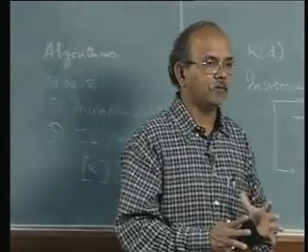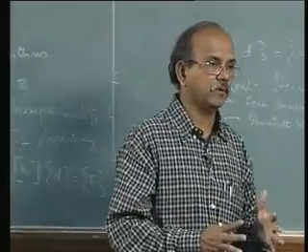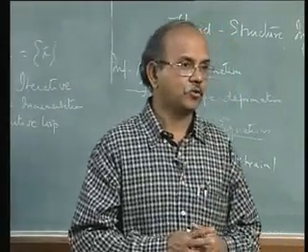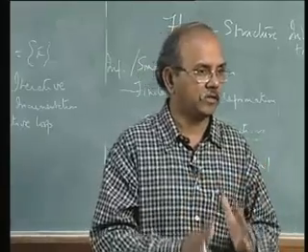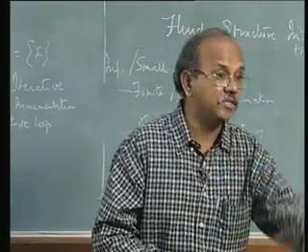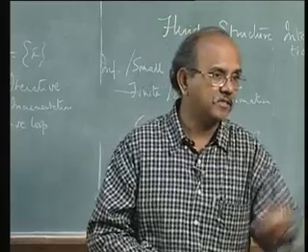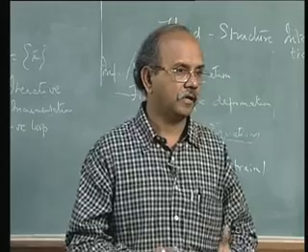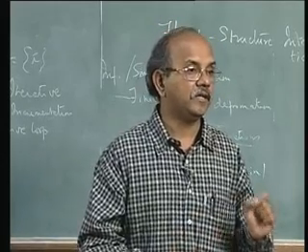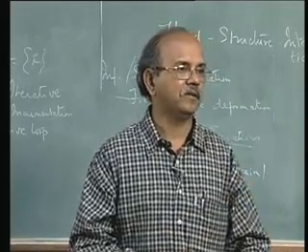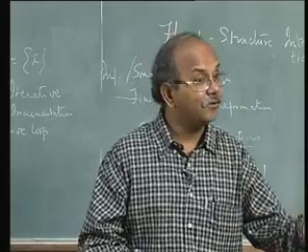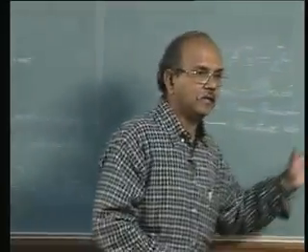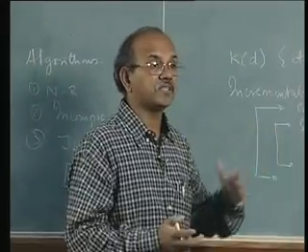When I say static problem, then time is not a factor. We do not consider inertia forces. So I apply this 100 Newton or 1000 Newton, whatever it is, and I do not invoke that inertia force. MA does not exist. It's so small that you neglect it, right? And keep applying the load, and your final interest is at the point when whatever load you had applied is under equilibrium with the stress. Is that clear? So it won't be any different as long as the process is static.